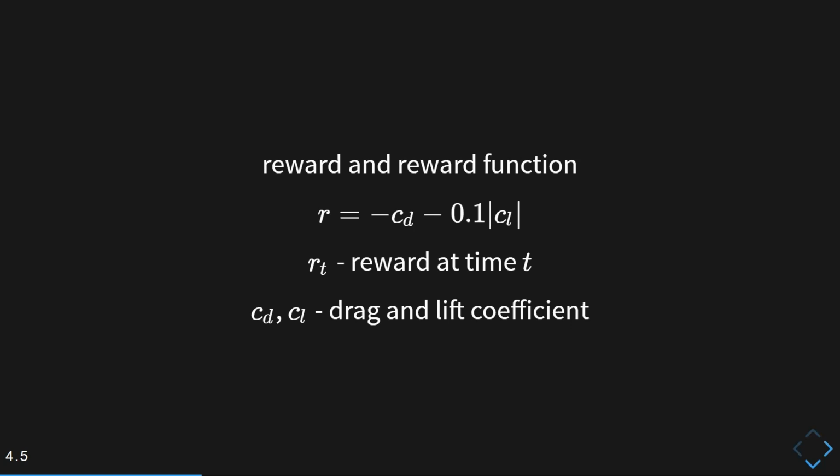And you could basically counteract this behavior by introducing a penalty on the energy that is consumed, right? Which is something based on the change of the angular velocity. In this case, you can also get the same effect by including the lift coefficient in your control objective. Because of course, if you spin it very quickly in one direction, it will just increase, and it will create a very large lift force.